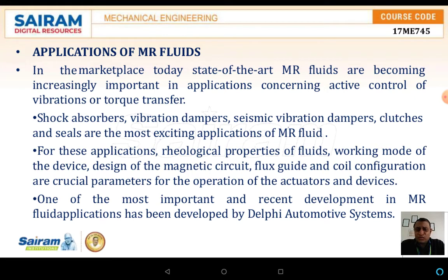In the marketplace today, state-of-the-art MR fluids are becoming increasingly important in applications concerning active control of vibration or torque transfer. Shock absorbers, vibration dampers, seismic vibration dampers, clutches, and seals are the most exciting applications of the MR fluids. For these applications, the rheological property of the fluid, the working mode of the devices, and the design of the magnetic circuit, the flux guides, and the coil configuration are the crucial parameters for the operation of the actuator as well as the devices.